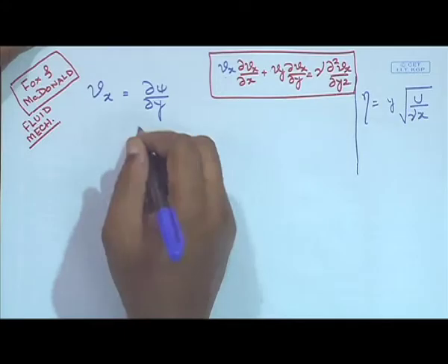So right now we are trying to find out the expressions for Vx, Vy and all other terms in the equation of motion in terms of psi, the dimensionless dependent variable, and eta, the dimensionless independent variable. The expression for eta we have already obtained based on an order of magnitude analysis. So I am going to show you how to get the expressions for Vx and Vy. The other terms of the equation of motion can be seen from the textbook Fox and McDonald. So let's see how we do Vx in this case.